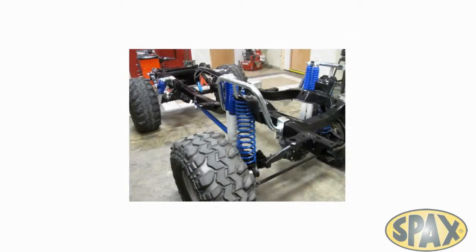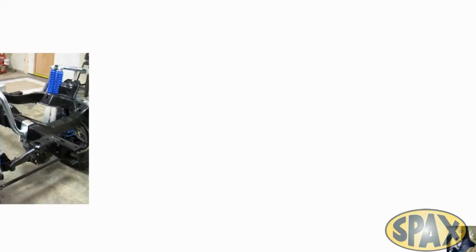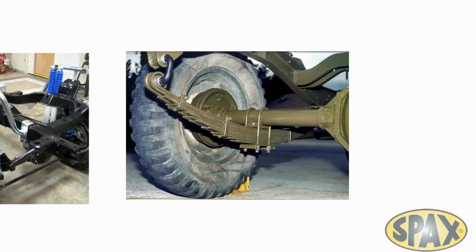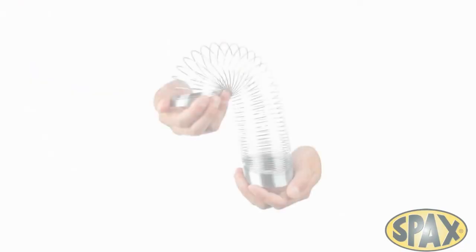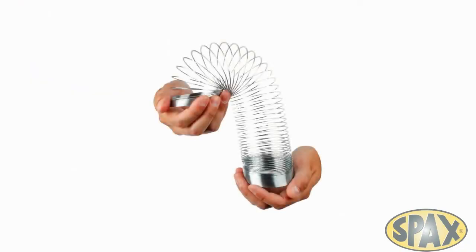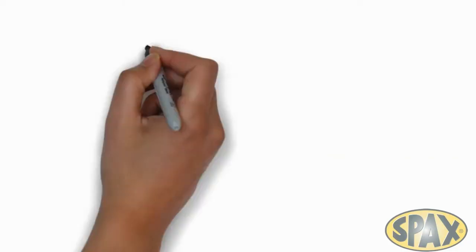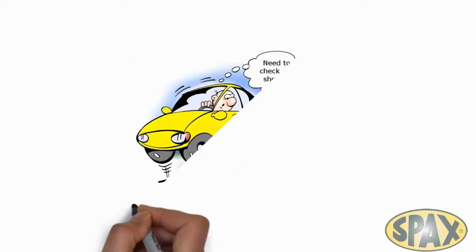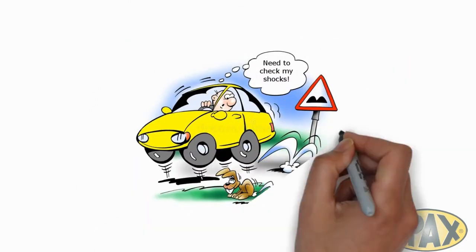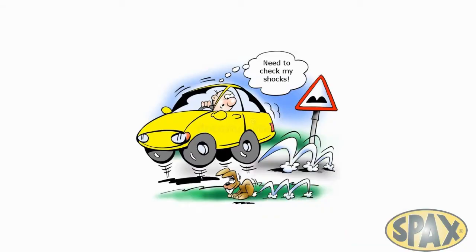Springs are energy storage units, whether coil springs on modern cars or leaf springs on older or commercial vehicles. All a spring can do is store and release energy. When suspension springs are compressed, they store motion energy from the force pushing in, and when the external force is released, the stored energy expands the spring. Springs aid passenger comfort as they cushion the external forces encountered as the car is driven, but if a car only had springs, it would constantly cycle the stored and released energy and the vehicle would continuously and dangerously bounce.